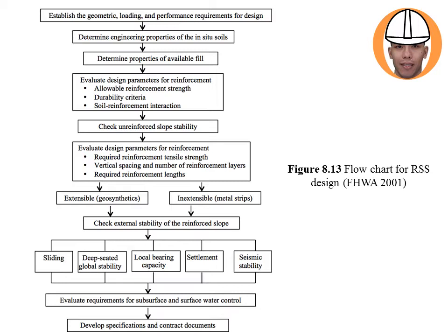So you have the check for overturning, check for sliding, check for bearing. So those are some. You also have the settlement, and then the seismic.